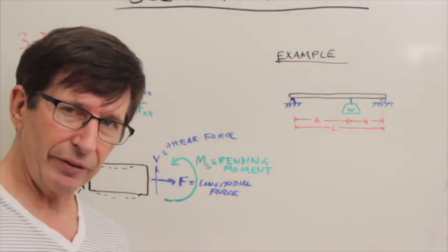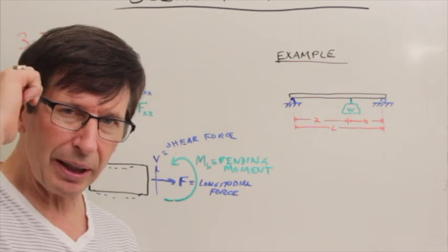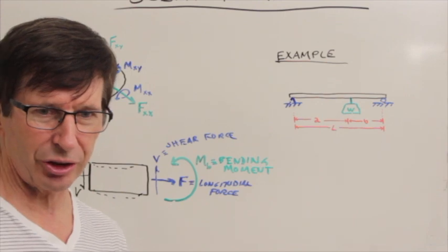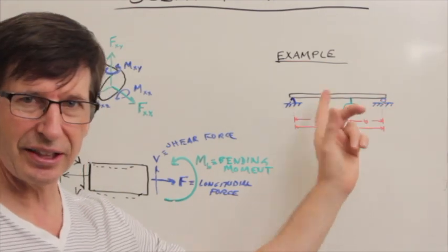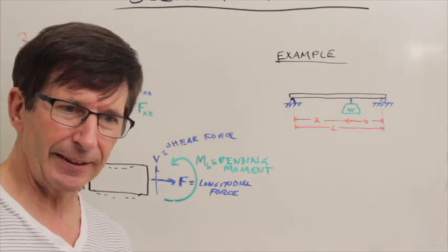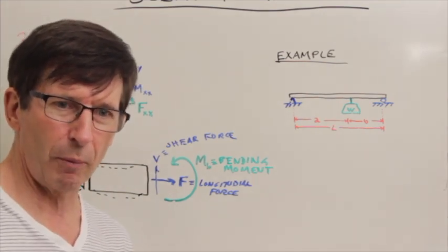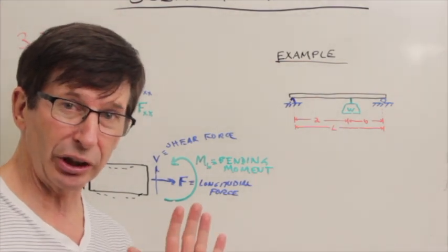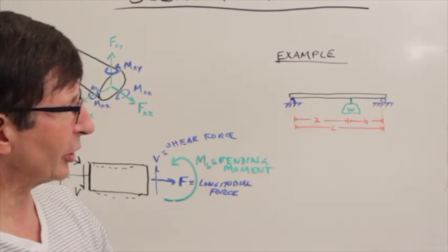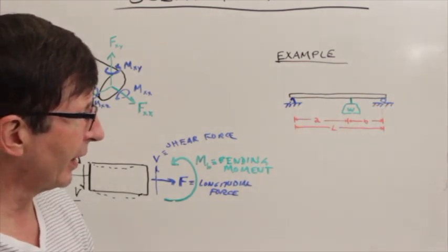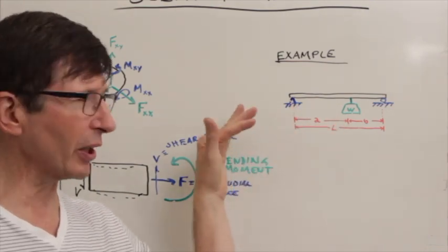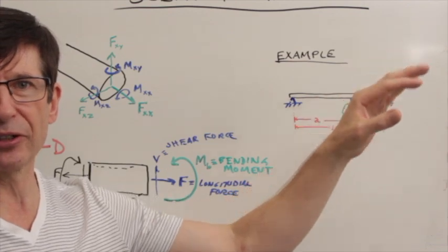But in this video, in this lecture, we're only talking about equilibrium, so we're not going to worry too much about constraining things like this x displacement from happening, because that will be left for a more advanced treatment of, gee, how much would it tend to get shorter? But these are the boundary conditions on our beam. And the only reason we want to restrain it in the x direction one place at all is to stop it from zipping off into space.